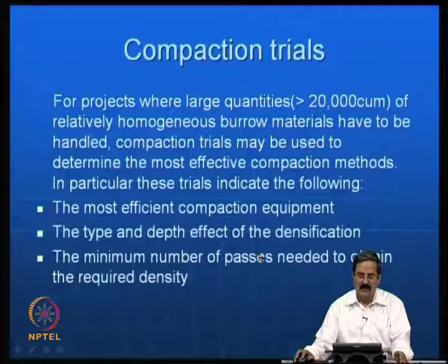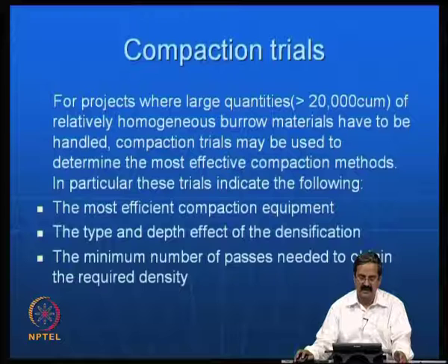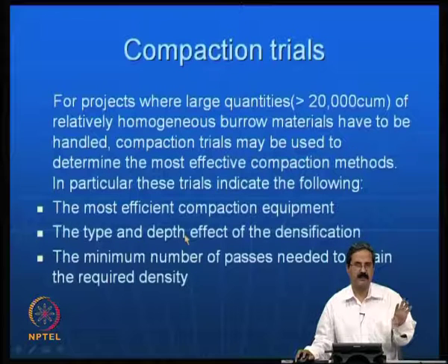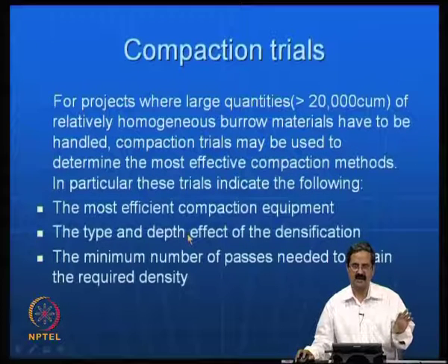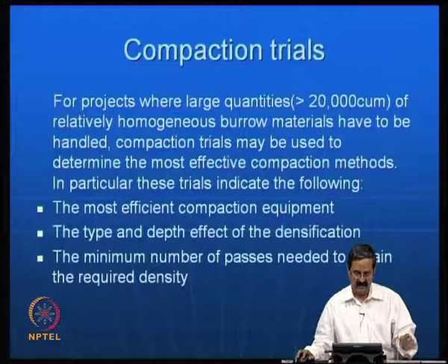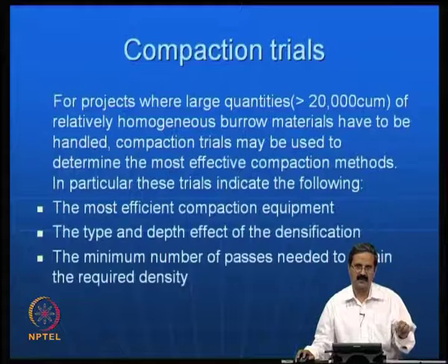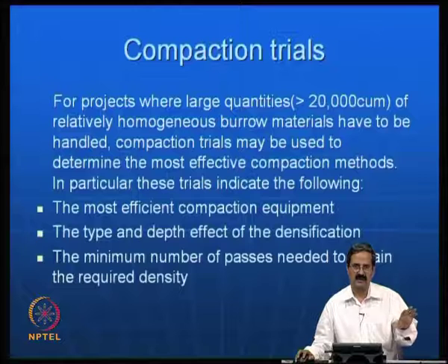Sometimes, in a big project, the advantage would be that you do compaction trials. Going by certain specifications is one thing, but try to come out with project-based specifications. You have a big area, and somebody has some 10,000 crores project for an embankment. It is better that you have specifications based on the material available there, and try to understand the soil behavior of the materials.